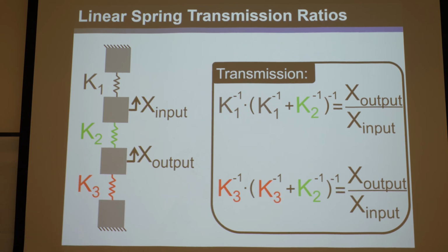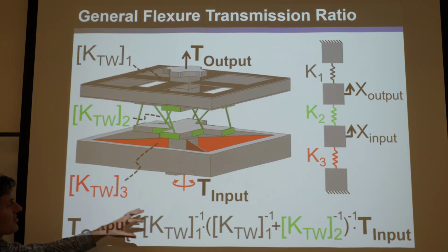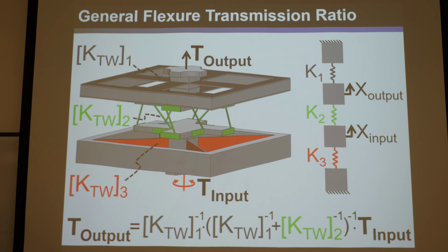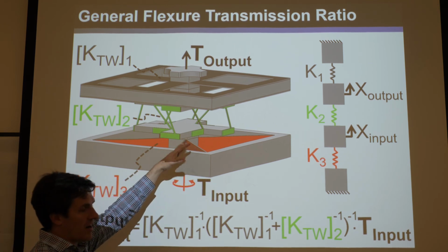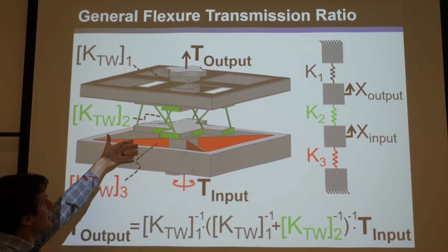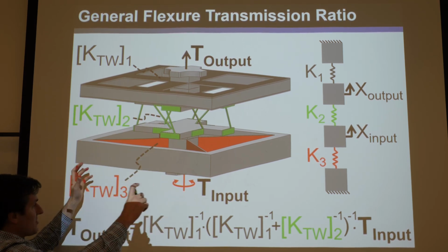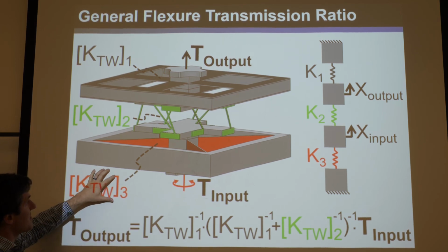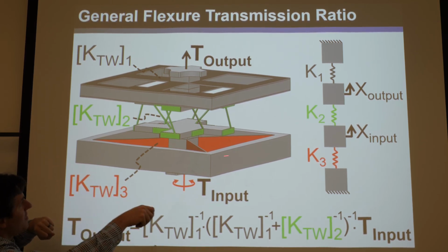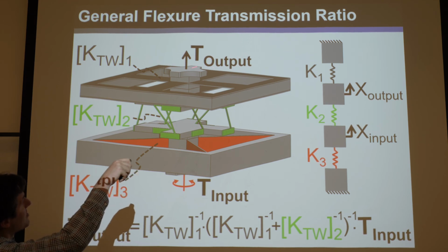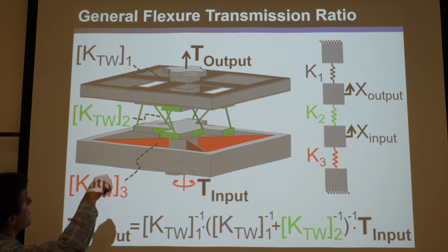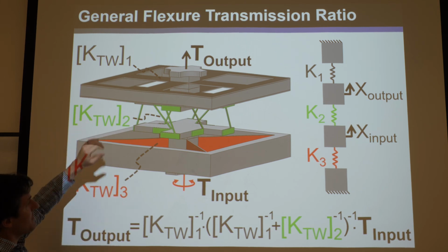But remember, in our one-dimensional idealized model with scalar springs, we can apply the exact same ideas with our stiffness matrices from lecture 3. We can take 6 by 6 stiffness matrices that capture the stiffness of entire parallel modules. The elements in red are in parallel, so you add them all together. So you can have a twist-wrench stiffness matrix for this parallel module, then the one for the flexures, which I show in black, has this stiffness matrix. Then the screw in green has this stiffness matrix.